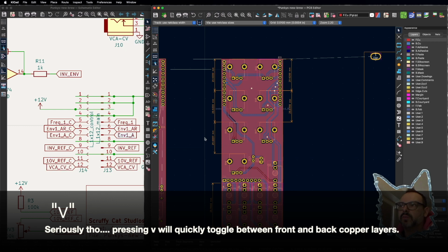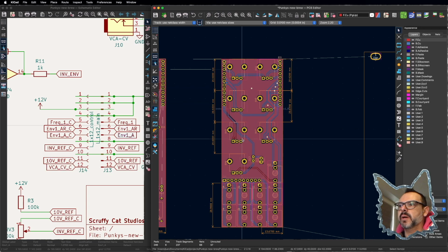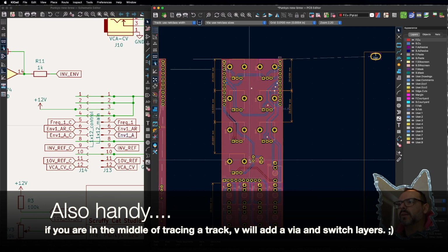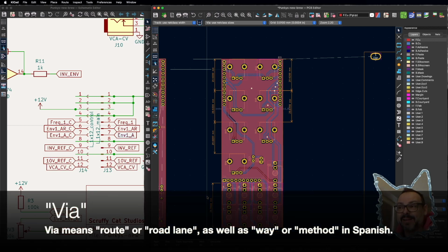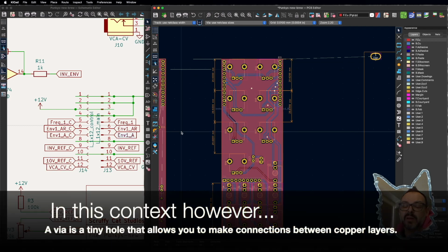A few things to talk about here is, I tried to keep my tracks relatively tight. So this makes it a little bit easier when I have to cross them, like if I had to use a via to go into the other layer. Especially since I'm not arranging the board for optimal tracks, but rather for more ergonomics, right? Because this is a board that's going to be dependent on how you intend to use it.